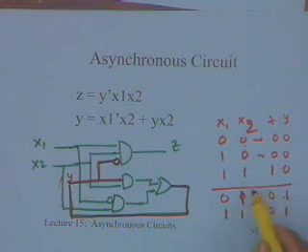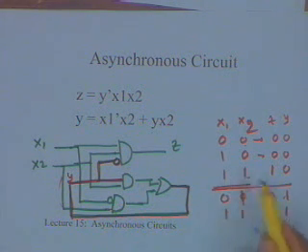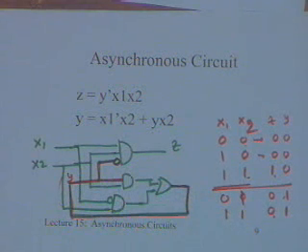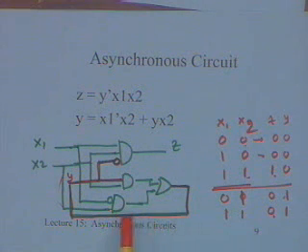So for the same x1 x2 of 1, 1, this is going to be 1 here and this is going to be 0. I am going to get two different outputs, and that is essentially ensured by this particular feedback path. Remember that we are not providing for any additional delay, it is only the internal delay of the gates. Okay, so we will stop here, we will continue.